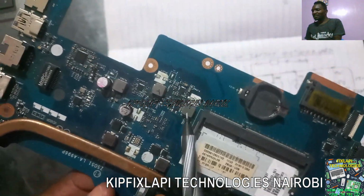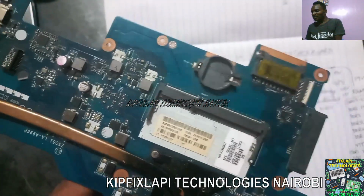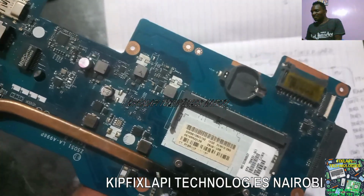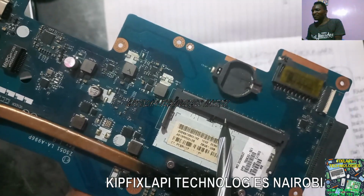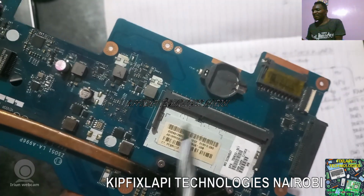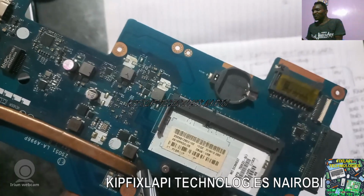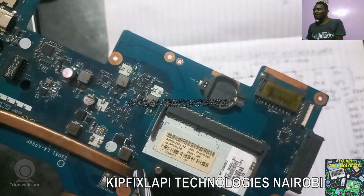Then apart from that, we also have the circuit which supplies them. So this is the CPU. Inside here we have the CPU. Then here you have the circuit which is responsible for the RAM. This is for RAM power supply. So this is DDR3. So I expect at this inductor, the output of this circuit will have 1.5 voltage, because this is DDR3.